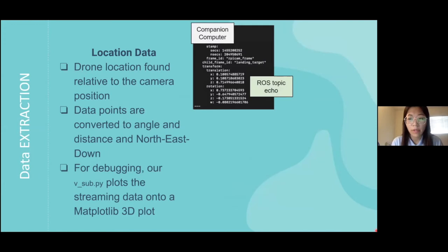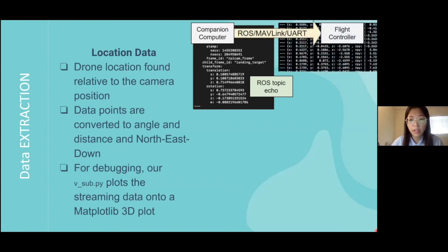And this node would help convert angle and distance according to east-north-up conversion with user input roll, pitch, yaw, and gamma angles. We do one more transformation into a north-east-down frame, which is used by our flight controller. After the flight controller gets the data, we use the MAVLink shell, which is used for running commands and displays the output. At this point we are able to see what message contents were received for VisHawk.